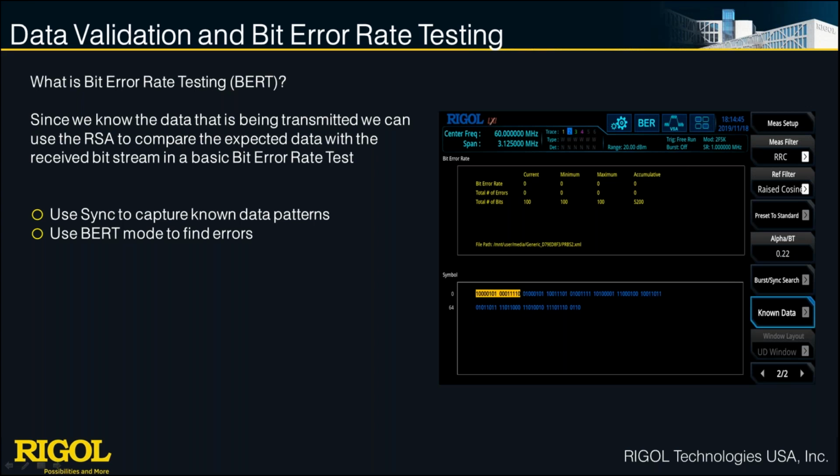So we've got the ability to say that the data we were putting out of the transmitter, or putting into the serial link originally, that we then improved and decoded, we're now getting that same data sequence every time coming through the modulation up on the carrier and being demodulated. So we've got really good data integrity throughout our entire system by being able to look at the debugging through this whole chain of events: decoding, jitter, eye diagram, up on carrier, frequency analysis, demodulation, and finally bit error rate.